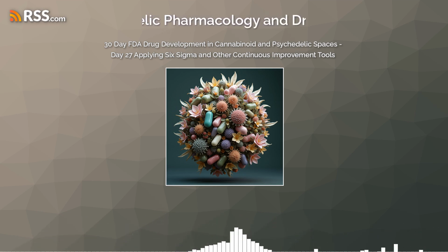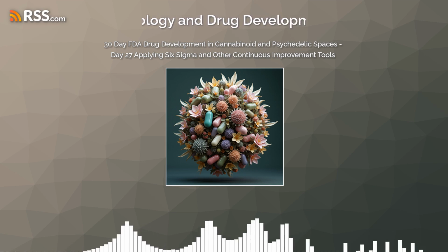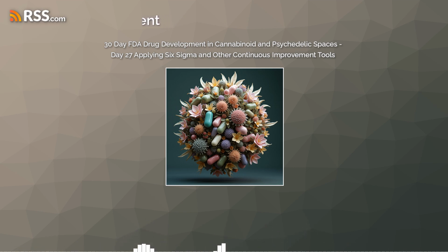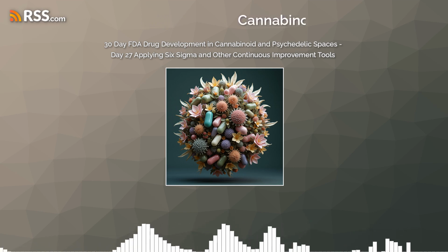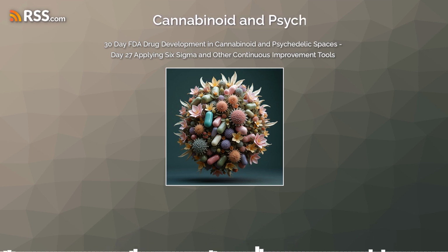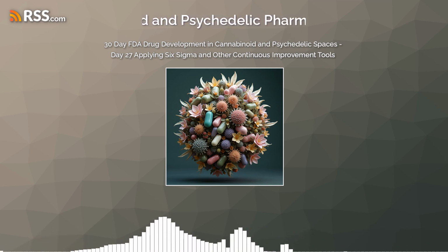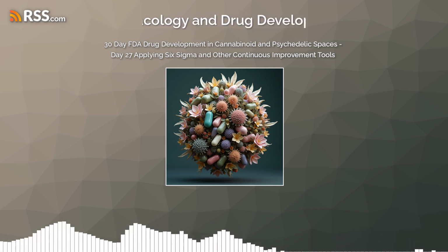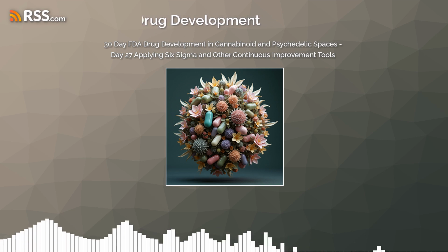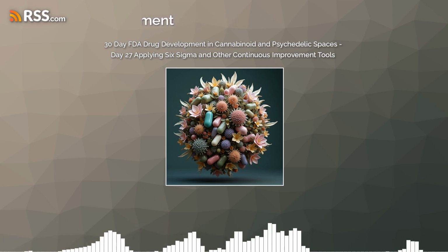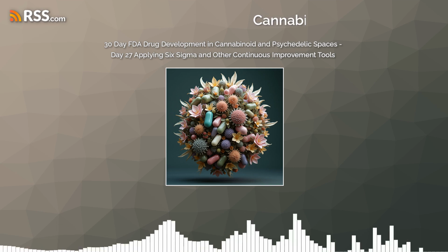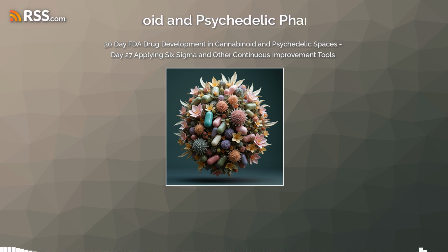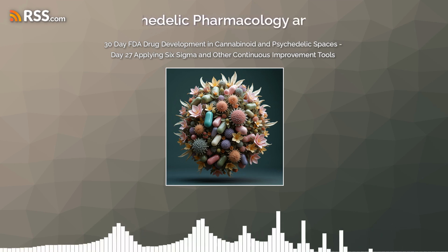Yeah, it is. It's basically a way of visualizing the results of a DOE experiment. Okay. So you can imagine it like a map of the process, and the different contours on the map represent different levels of whatever quality attribute you're interested in. Okay. And you can see how changing the different parameters moves you around on that map. So it's almost like having a GPS for quality optimization. Yeah, that's a good way of thinking about it. And that allows you to not only find the best conditions, but also to see how sensitive the process is to changes in each parameter, so you can design a more robust process.